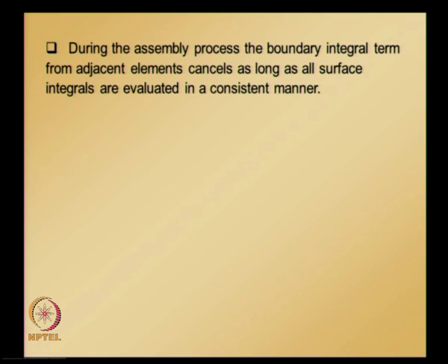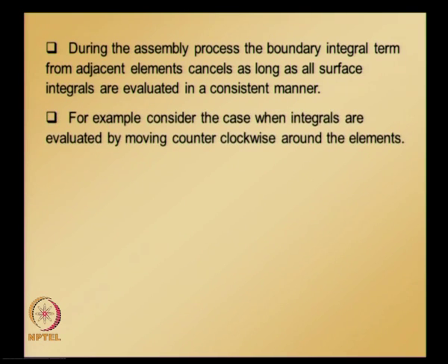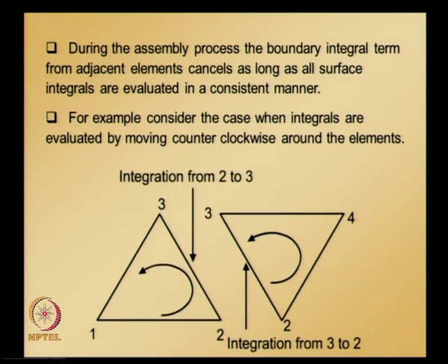And now this integral on the boundary: during the assembly process, the boundary integral terms from adjacent elements cancel as long as all surface integrals are evaluated in a consistent manner. To understand this statement, let us consider the case when integrals are evaluated by moving counterclockwise around elements like these two elements.